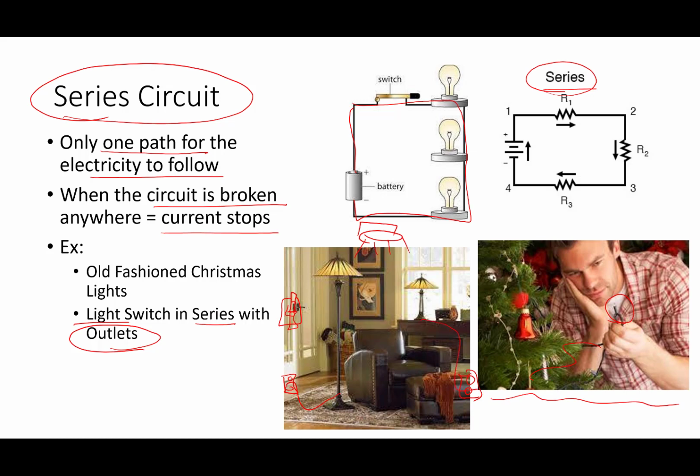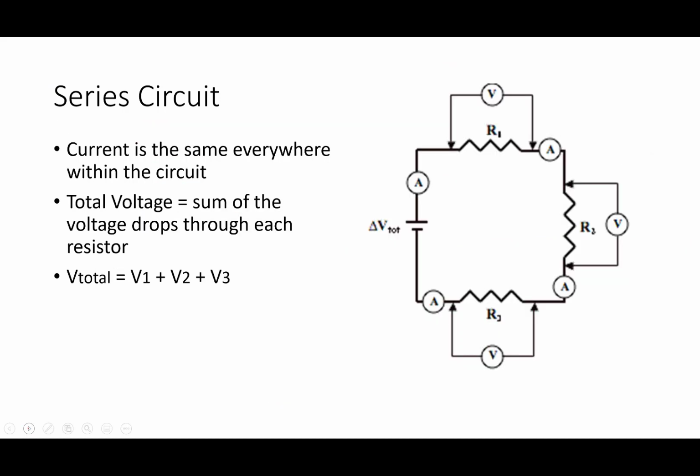So you can have lamps, all this lovely romantic mood lighting around the room, and the switch is in series with the outlets. You turn it on, all the lamps come on. You turn it off, all the lamps turn off. In many rooms, it's only the top or only the bottom plug that is in series with the switch, so you can still have other things plugged in.